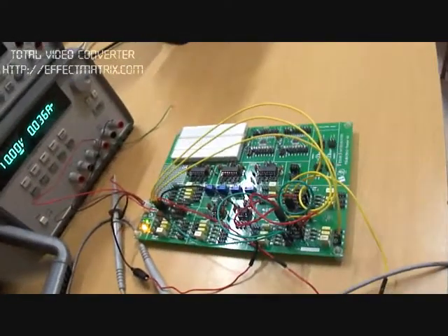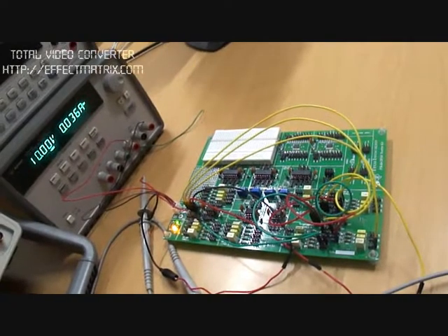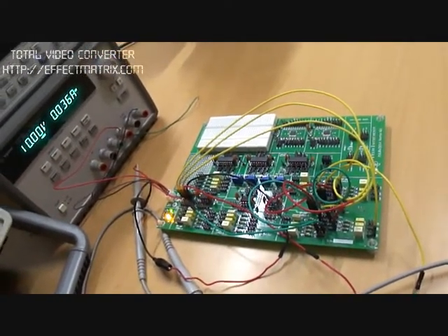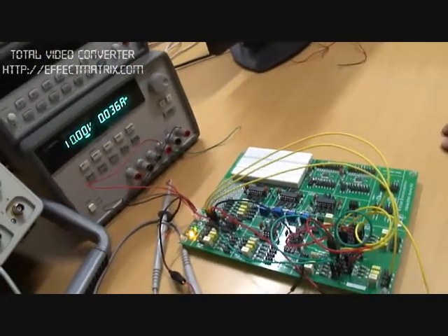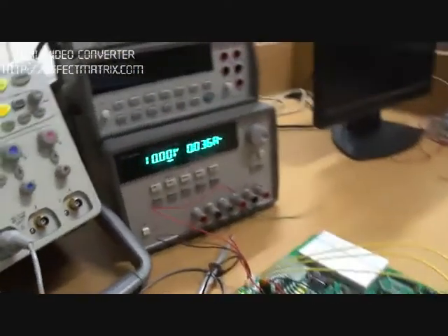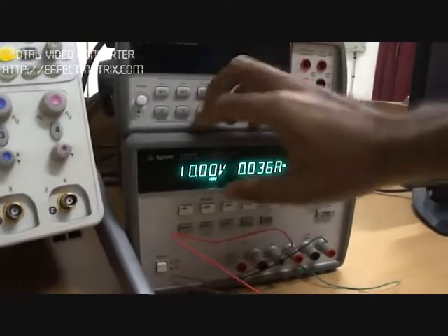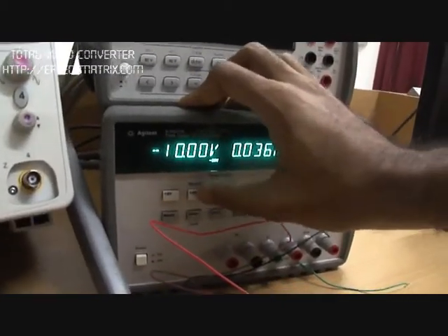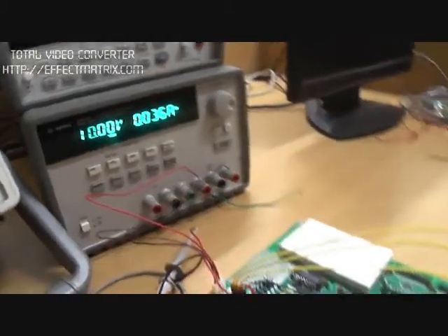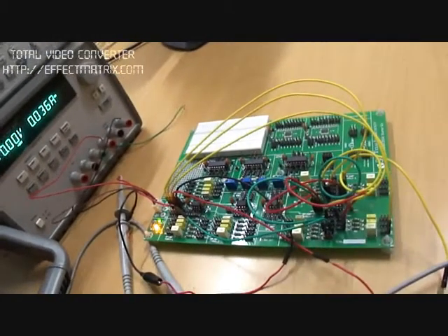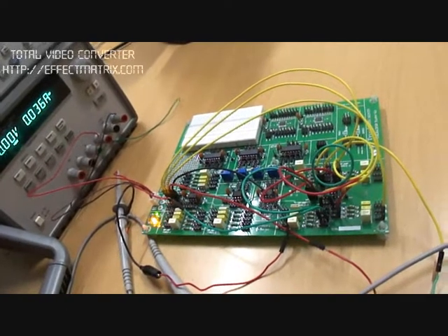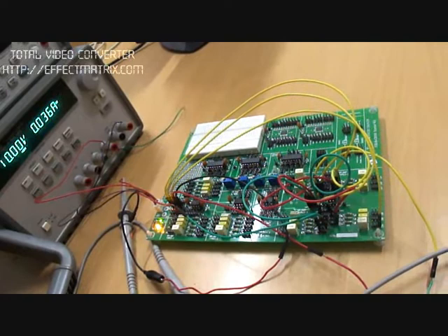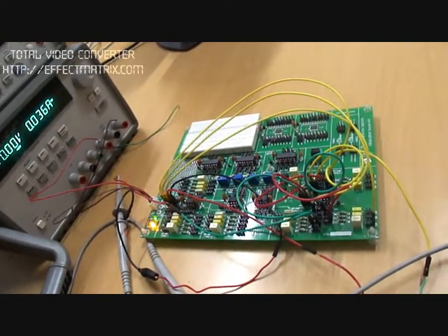This is our lab setup. We have built the function generator circuit using the ASLK kit, as you can see. The ASLK kit is supplied with a DC power supply of +10 volts and -10 volts. We have used op-amp IC4 because it offers both inverting and non-inverting configurations suitable for our circuit.